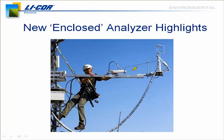Something else that's important about the 7200 is that because it's weatherized and it can be placed at the top of the tower near the sonic anemometer, you can use a short intake tube. Dave Johnson is going to discuss the benefits of that short intake tube in just a minute, but I just wanted to mention it here because it is important, because we want to be able to get the analyzer very close to the sonic anemometer but not influence the turbulent air structures that we're trying to measure. And the 7200 really allows for that in a new way.